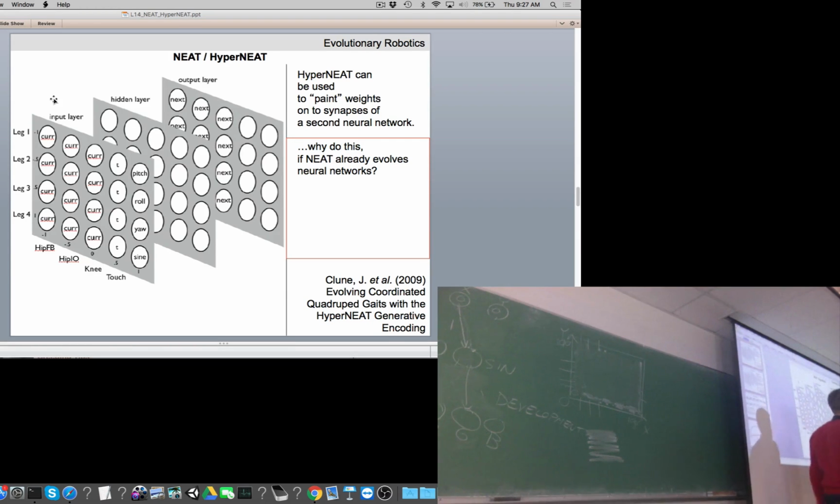What are these 3 reporting? They're reporting yaw, pitch, and roll, right? So it's reporting the overall orientation of the robot. So pitch is forward and backward. Roll is how much it's rolling to its left or right. And yaw is how much it's twisting about the vertical axis. So at every time step, this robot is going to receive these 3 numbers that tell it how it's changing its orientation in space. What's this one?